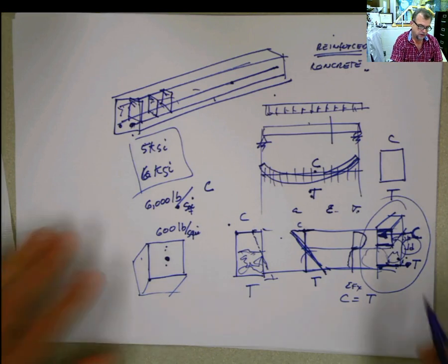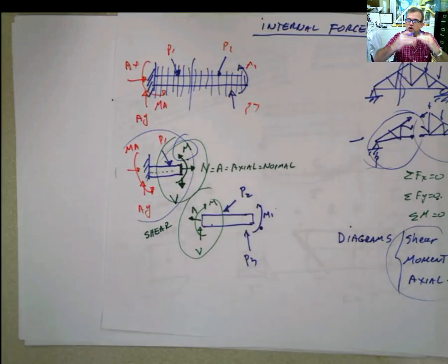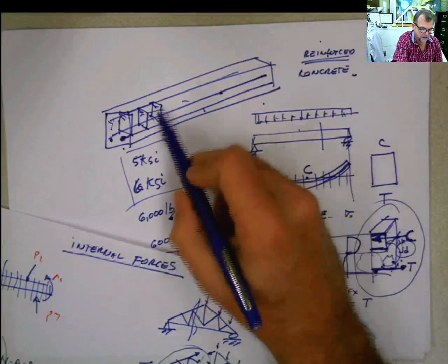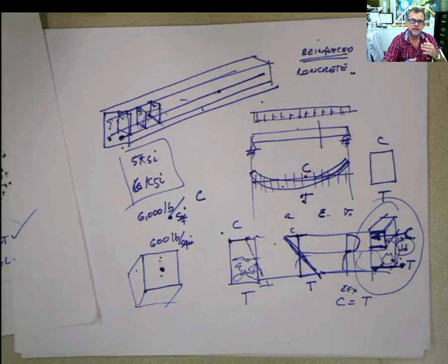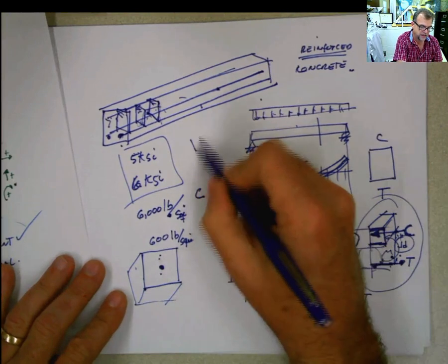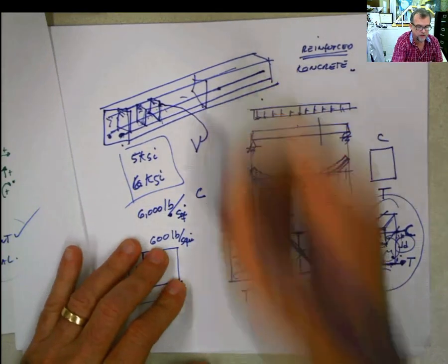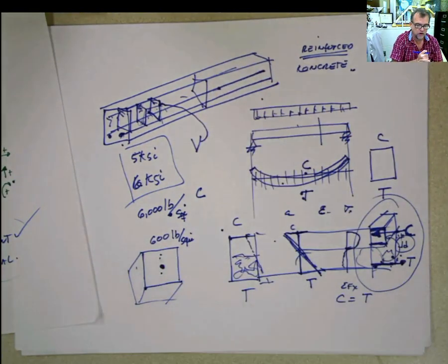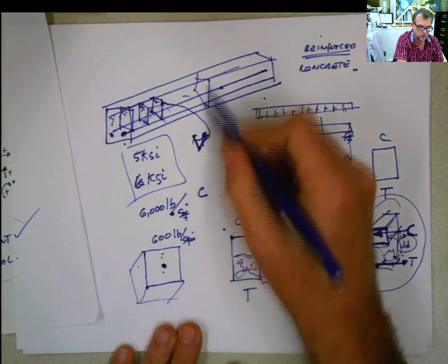What about the shear force? Well, shear is a force that is trying to cut the beam. That's why these elements here, the stirrups, are exactly designed for avoiding that cut to happen. So you use the shear, for example, in this case, to design that, and also the cross-sectional area, because you have to cut all the section. If you're gonna cut it in half transversally, the section is also gonna be able to absorb that shear.